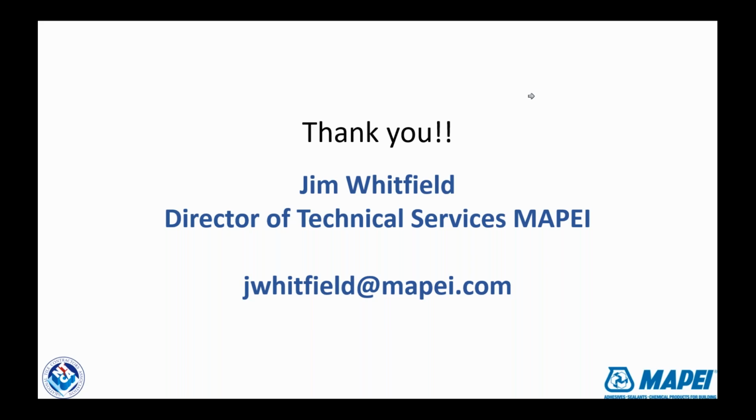There's a variety of ways to handle any outside corner with gauge porcelain tile, and exterior would be no different, except you've got sealant closing that joint instead of an epoxy or something like that. One of the things on all the tile installers' Facebook pages is they're very proud of how they can slip a dollar bill into a mitered outside corner. That may not be the safest thing interior. I mean, two sharp edges, but you really have to think about that.